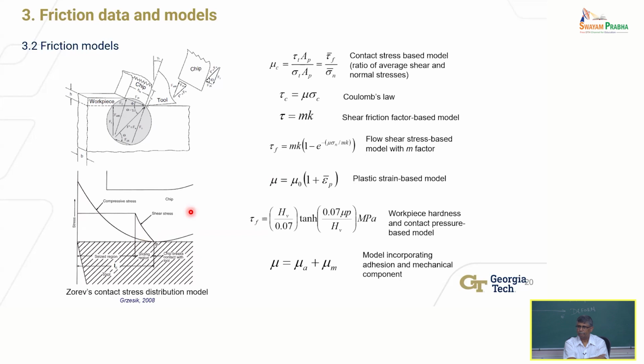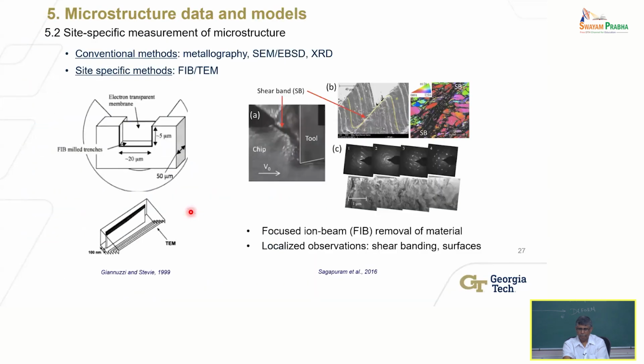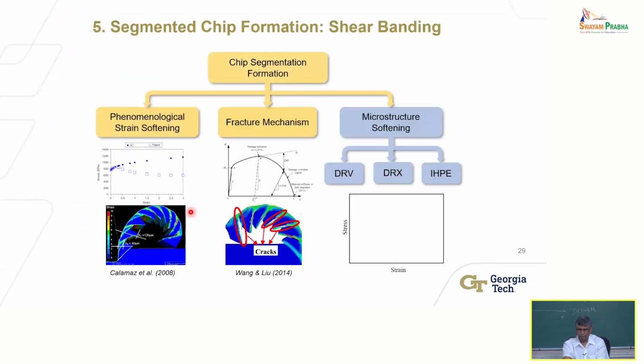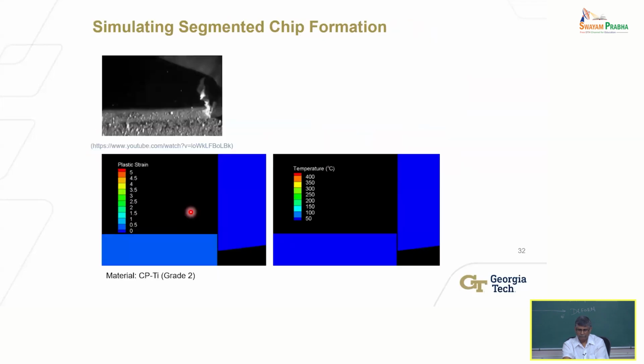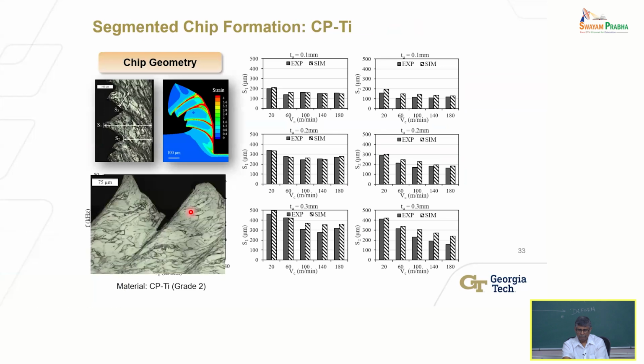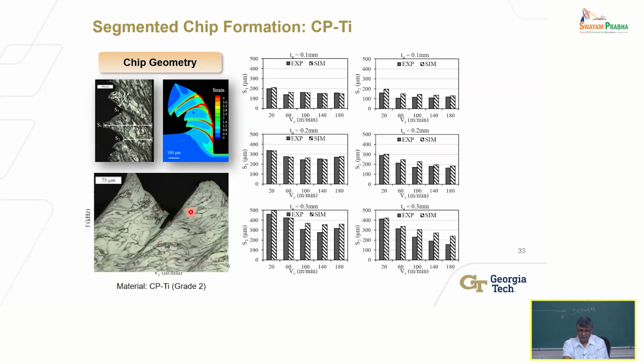Sir, I observed that you kept the rake angle at 0 and you changed the cutting speeds, and there were different chips with increasing speeds, right? Is there any work going on, especially on chip formation, by optimizing parameters or optimizing the groove geometry of the inserts? There has been a lot of work.